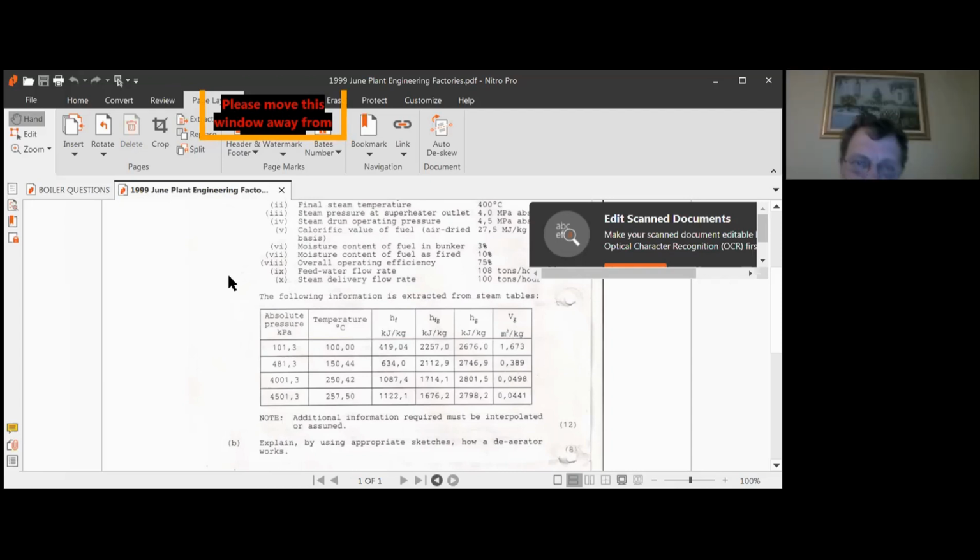No, I'll tell you why. The moisture content of the fuel in the bunker is just above the bunker that feeds the mill, and the mill grinds it, makes PF of it, pulverized fuel, and sends it to the boiler. The 10% is what I'm firing. So I'm talking about the heat as fired in the fuel, and I'll just use the 10% as it is.